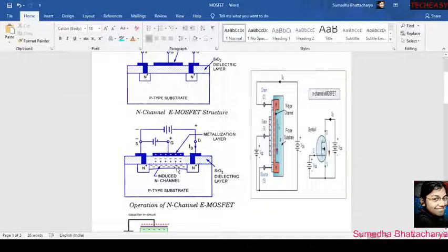So what will happen with the increasing of this depletion region? The current will be resisted from flowing from drain to source. Now there is also one more point, which is the pinch off region. Same case as for JFET, I told that there will come a time when the current will saturate for a voltage, and the value of current will not increase more.